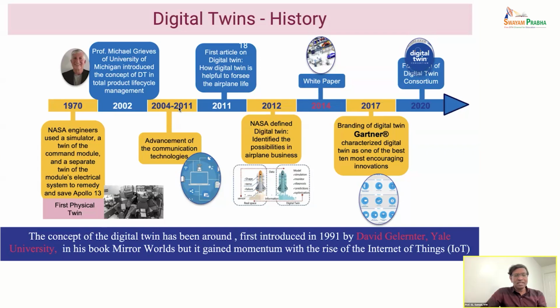Yeah. These metrology concepts used to be offline, but now metrology has become an integral part of manufacturing. Measurements and metrology have become an integral part of manufacturing. And also it is a feedback loop. So the loop is actually completed. It is not just inspect and then say the part is wrong, throw it away, reject it. No, that is not the thing. We need to get the information from it, why it happened, and then give it back to the system.